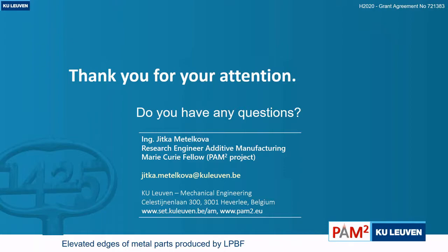And how many layers are going through the remelting process? Not just the last layer, right? Maybe the layer before last, several layers will be going through the remelting. We did the remelting only on the last layer. Only the last layer. Yes. I know from other groups, like for example in the US or Thailand, that in the last 3 years they stopped using the remelting. Maybe they have a different effect on the edge.